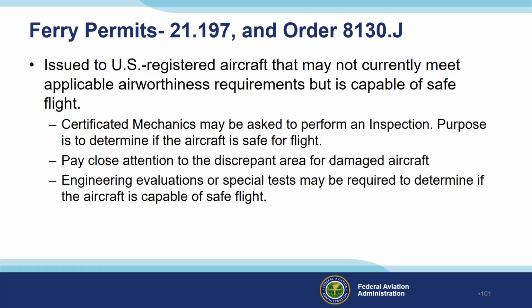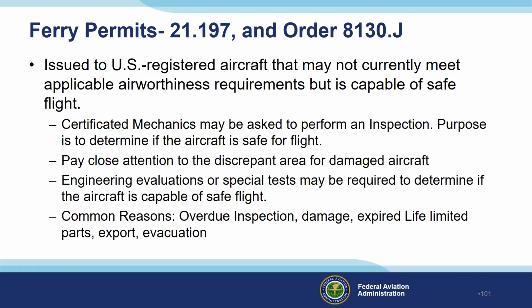You might need to get the manufacturer involved. You might have to get engineering involved. Common reasons for the ferry permit are overdue inspection, damage, expired life-limited parts, export or evacuation.